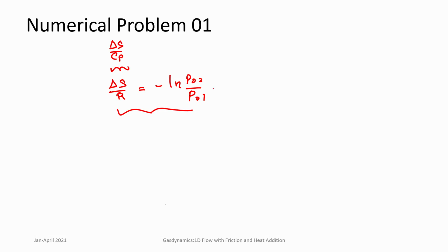Okay. So, here what are the stagnation changes? If you write P naught 2 by P naught 1, this can be expressed as P naught 2 by P naught y, multiplied by P naught y by P naught x, multiplied by P naught x by P naught 1, where P naught 2 by P naught y comes from the Fanno flow, Fanno curve, or those equations.